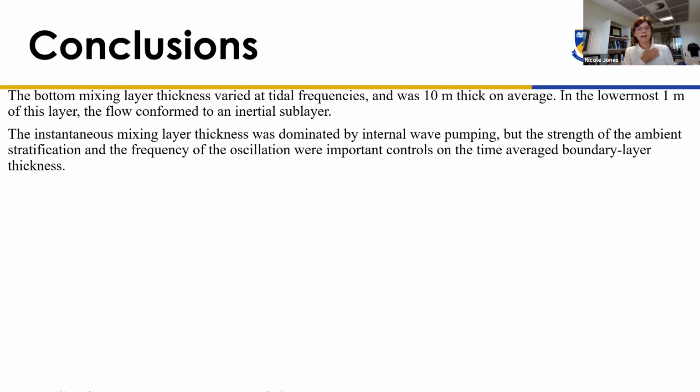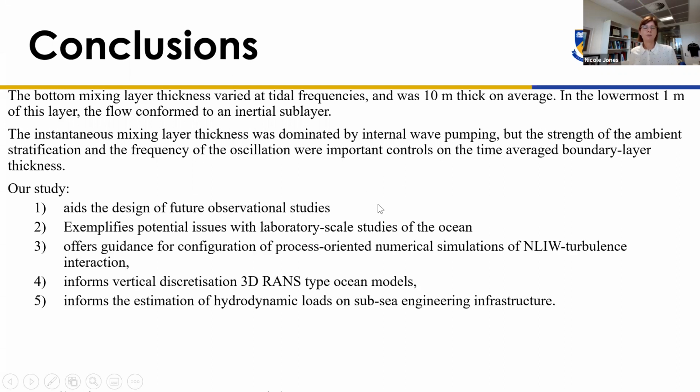And we found that at an instantaneous time scale, the mixing layer thickness was dominated by that internal wave pumping, but the strength of the ambient stratification and the frequency of the oscillation were important controls on the time average boundary layer thickness. And this gives us a nice way of